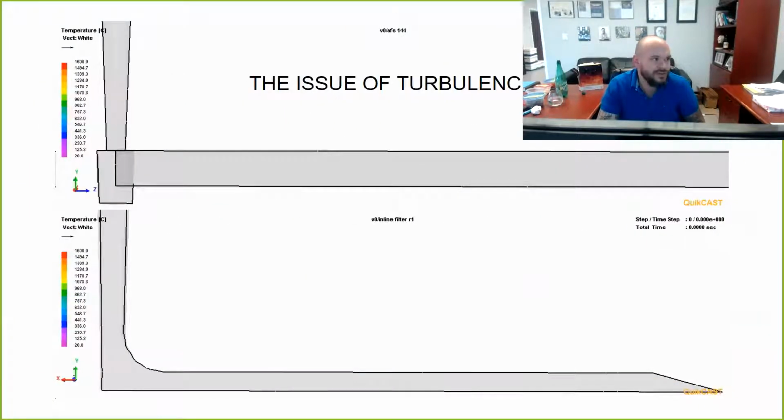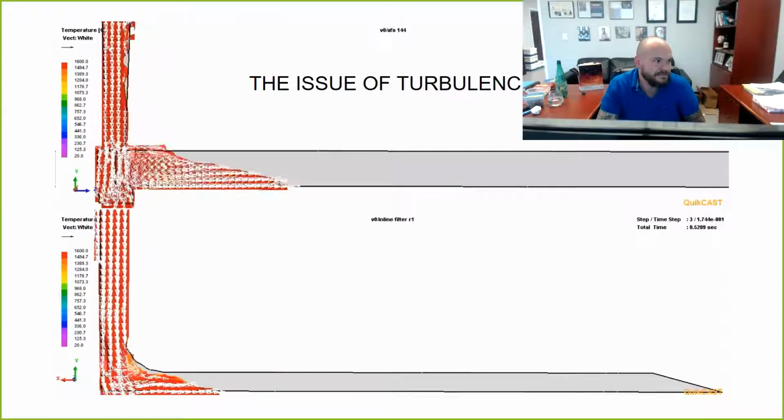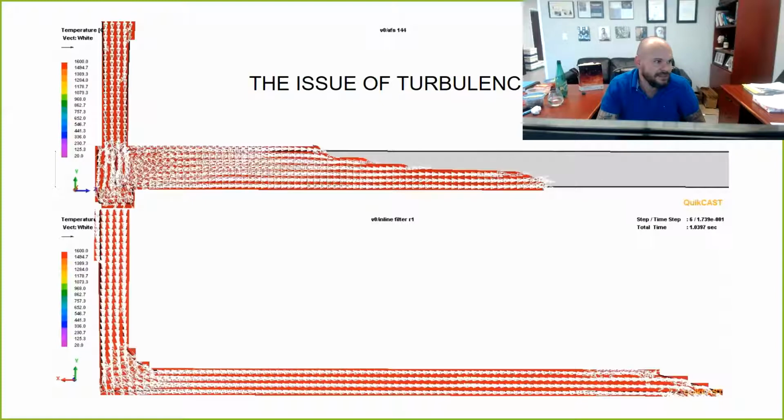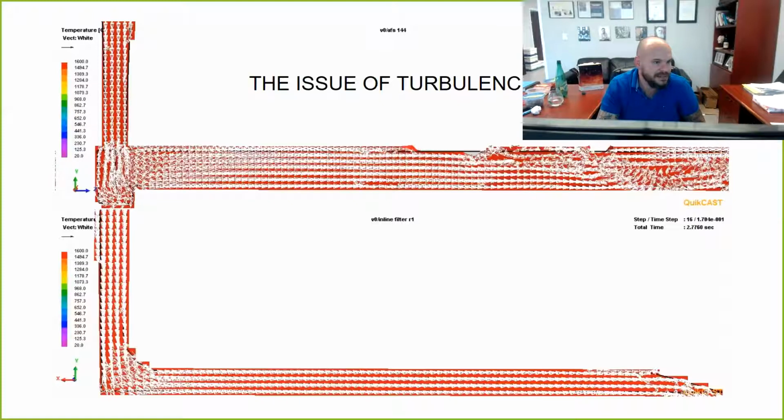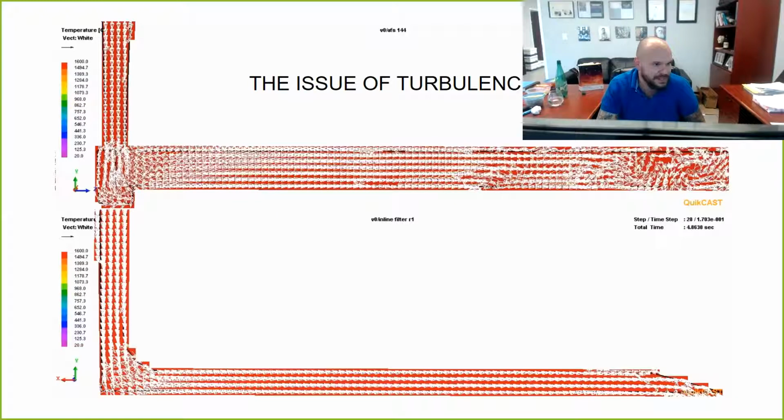This one will show velocity vectors. Look what's happening in that sprue well. And then look what happens as the metal is jumping along this unfilled runner. See that rolling back wave? See those pockets of unempty space? You see how the metal rolls back on itself, entrains the oxide film, pushes up against the surface, which is pushing that air through as a bellows action. This is a complete mess, right?